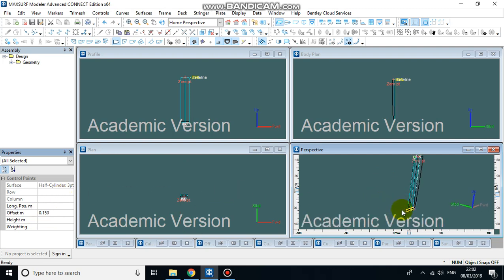And then lastly, we're going to bring the bottom up to near the gunnel here. So I'm going to select all the points down the bottom, and I'm going to go with negative 0.1, which will give us 100 mil from keel to topsides, or keel to gunnel. Now when we zoom in, we've got a much smaller half cylinder, like so.